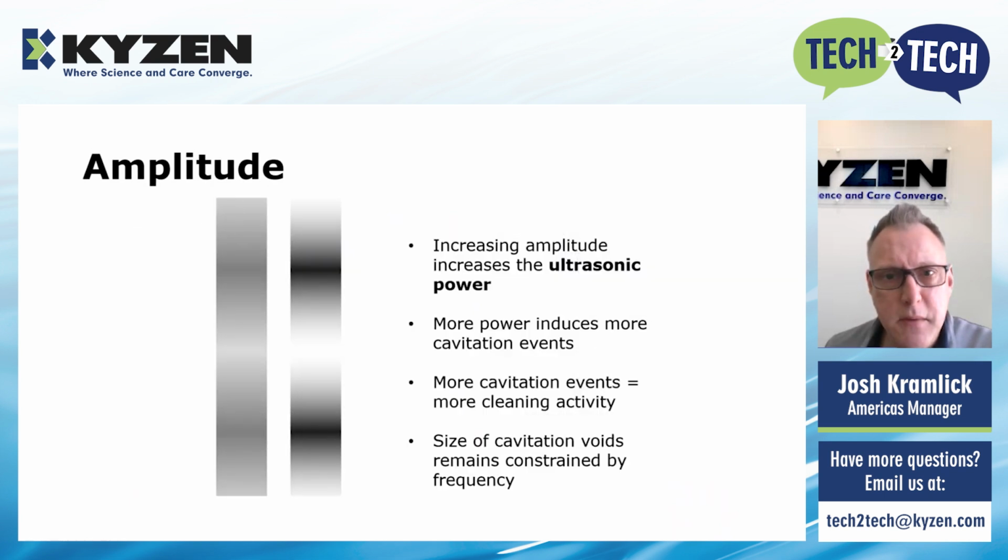So we have another similar animation here. On the left and right are the same frequency. The left has a lower amplitude than the right. As we increase this amplitude, we increase the ultrasonic power. That additional ultrasonic power induces more cavitation events within the bath.